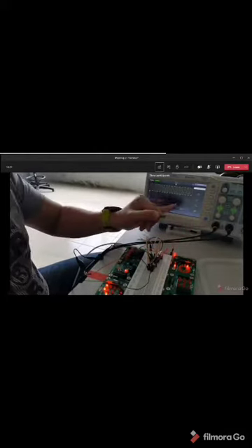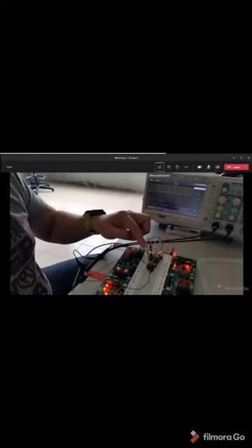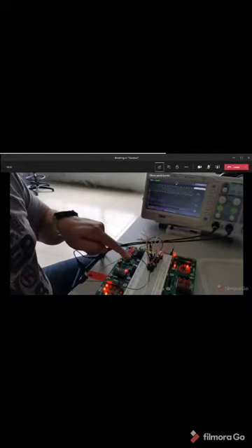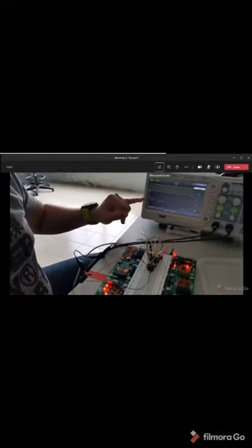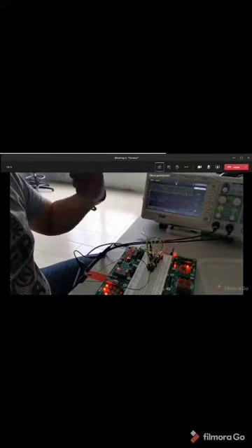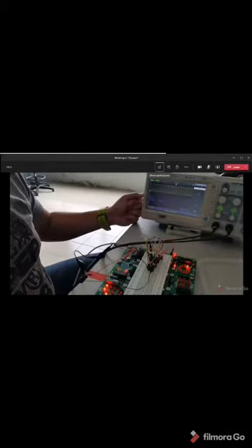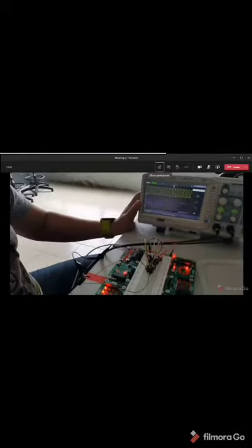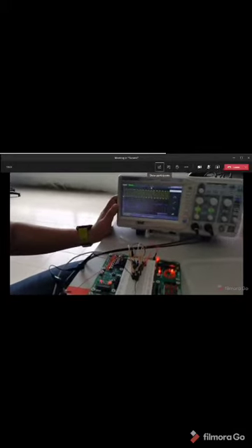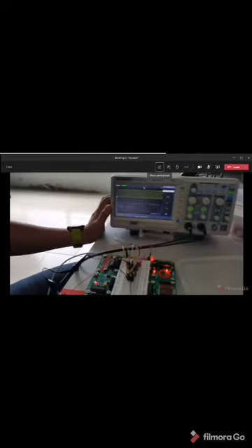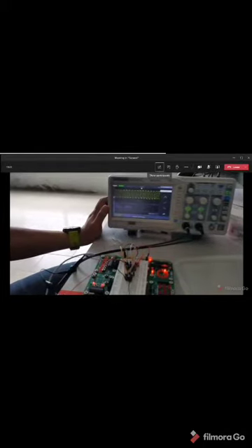we are going to jumpstart the whole circuit, and for that we are going to use the extra XOR gate. So for our 3-bit shift register, what we are going to do is, after connecting the X1 and X0 using a XOR gate, we are going to connect that output to another XOR gate, and that XOR gate is going to be connected to a switch, and through the switch we are going to input active high logic. That means we are going to input 1,